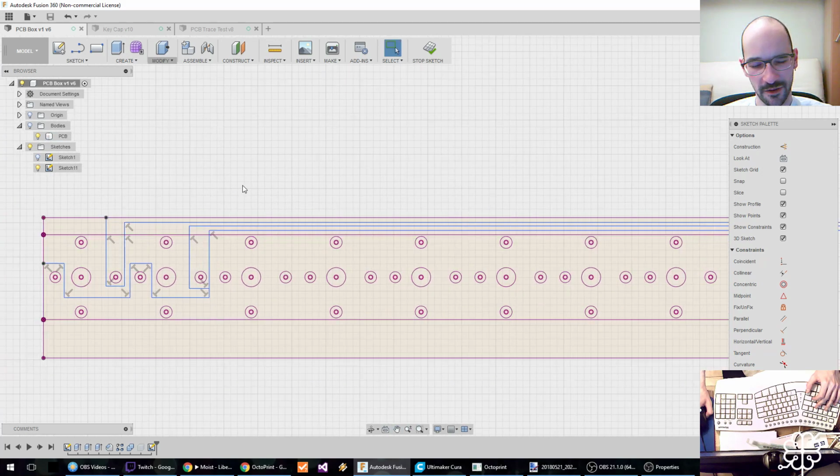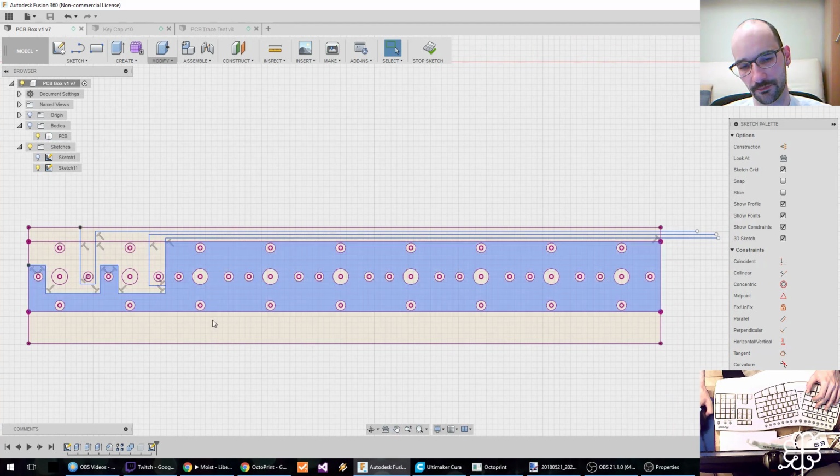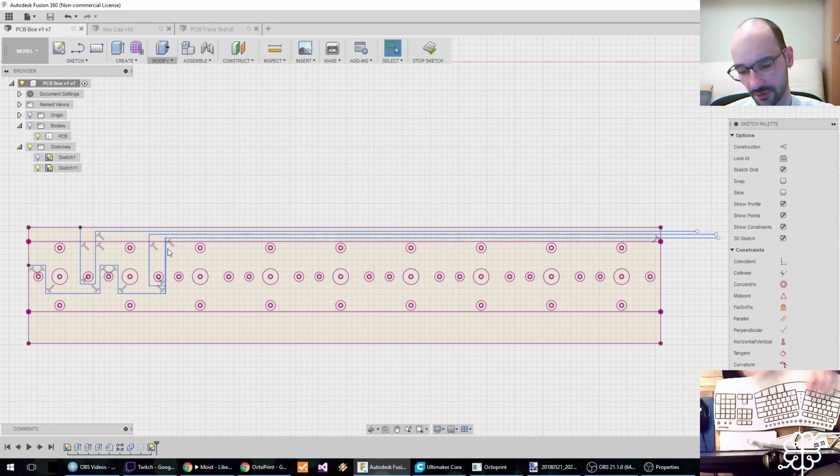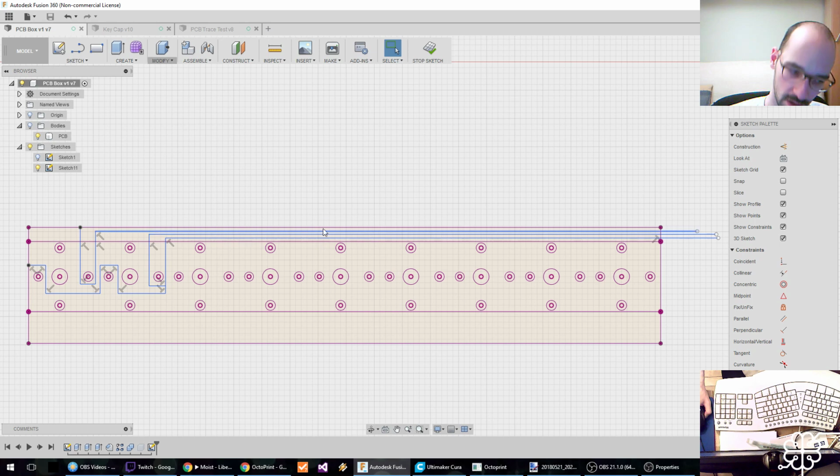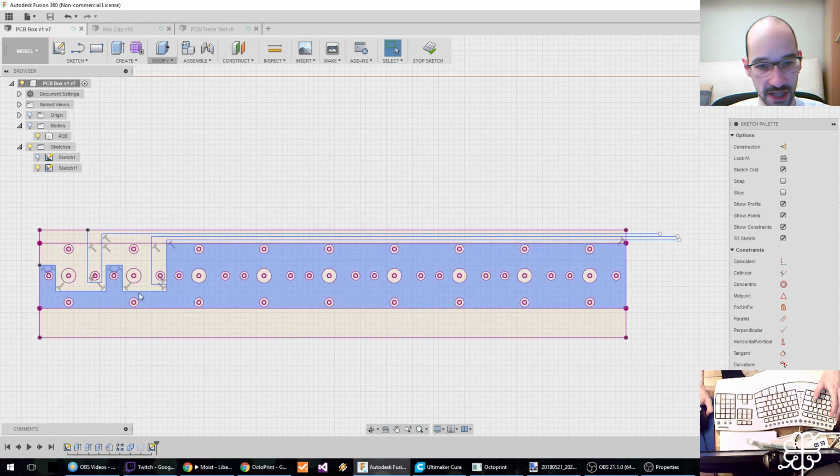Yeah, I think my ideal vision for these types of printed circuit boards would be to actually take a layout, like a Gerber file from Eagle or KiCad or whatever open source design tools are out there, and actually convert that to an STL file, a 3D printable version of the circuit that you then just put the copper foil over, and you run your knife down it and everything works. Now this manual isolation routing is a bit of a pain, I admit.